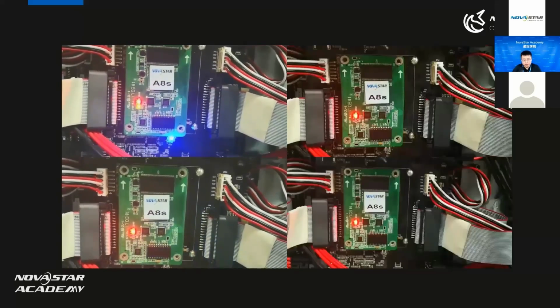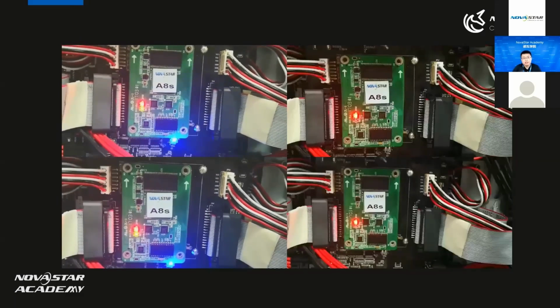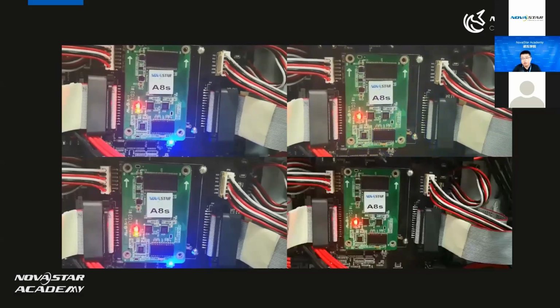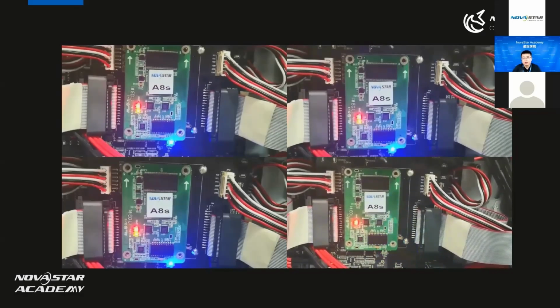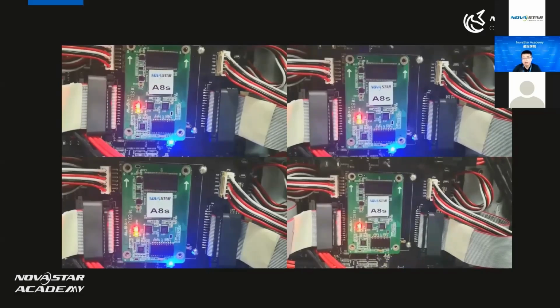And the top left corner, it is in backup mode because you can see it fast flashes 4 times and waits half second. How about this one? This is working normally because it flashes once per second. And this one is no video source connected. It fast flashes 3 times and waits half second, and then fast flashes 3 times again.